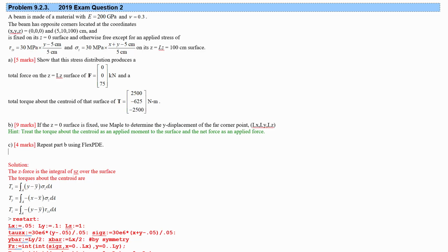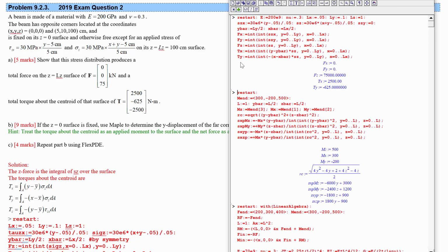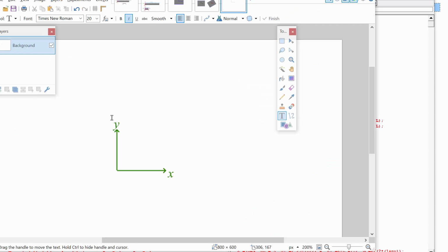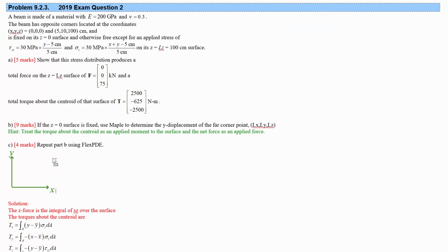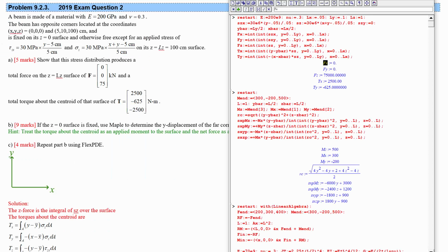And then the last one is, how do we find the torque about z for this? Let's get the picture back again. Maybe I can just copy this in so we don't have to jump around as much. Very helpful picture. Torque about z is going to depend on shear stresses. This is something we worked out in the notes as well, but we can just rethink how it works. We're going to have a stress on z in the y direction times the x displacement, which will give us a positive torque.